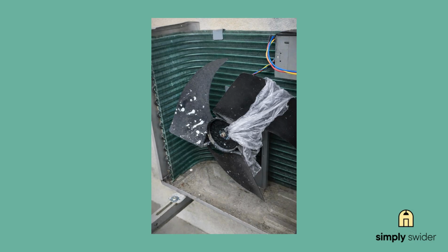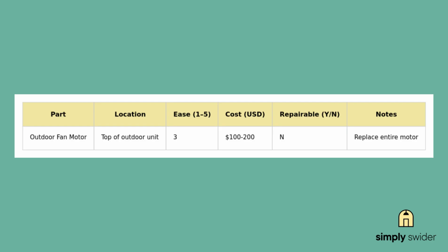If it spins freely, you're looking at electrical issues. I remember this customer who thought his unit needed a complete refrigerant recharge. Turned out a plastic bag had wrapped around the fan blade and nobody noticed. 5-minute fix, zero cost, way cheaper than the service call he was about to make.